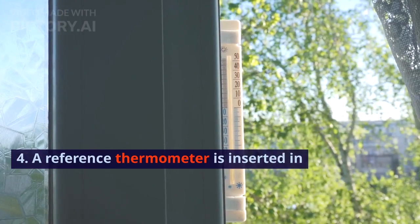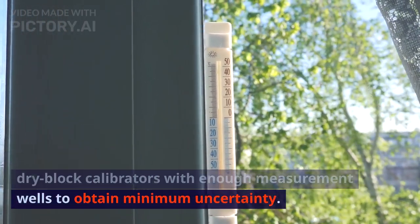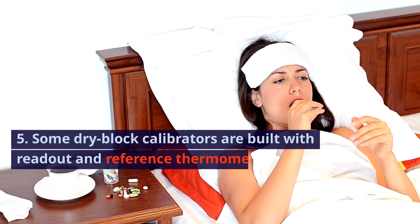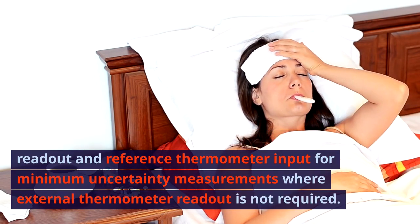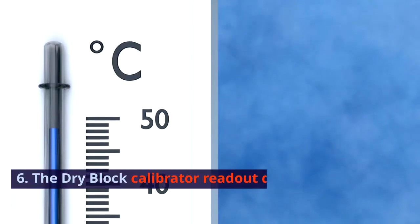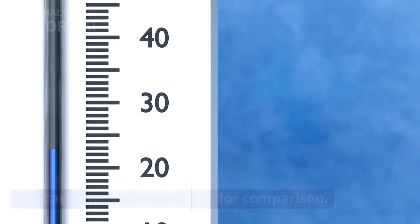4. A reference thermometer is inserted in dry block calibrators with enough measurement wells to obtain minimum uncertainty. 5. Some dry block calibrators are built with readout and reference thermometer input for minimum uncertainty measurements, where an external thermometer readout is not required. 6. The dry block calibrator readout display indicates both temperatures for comparison.